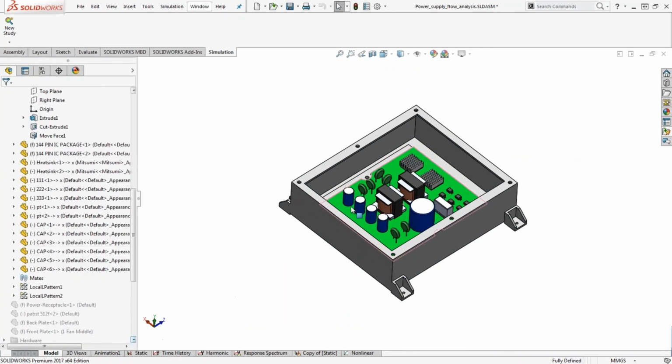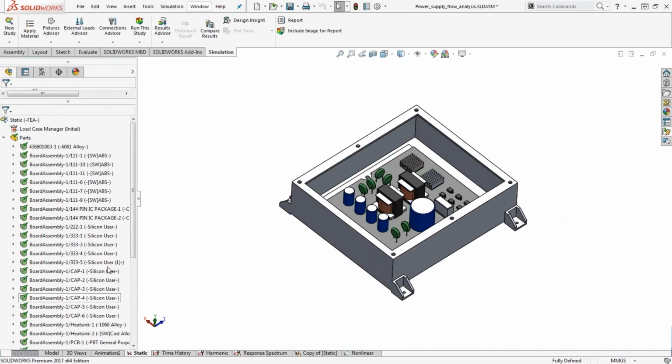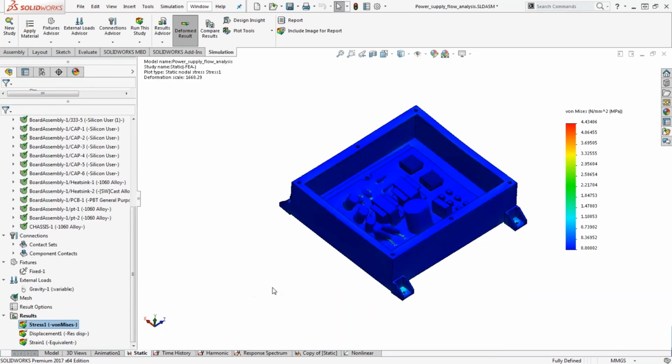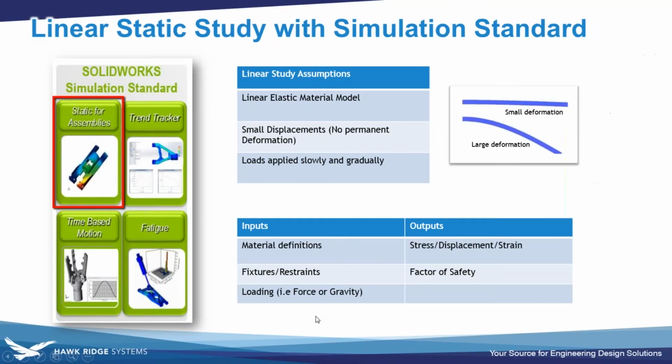So if I'm exceeding that yield strength, then that means that something has yielded or something is going into post-yield, where those max stress results are probably not going to be as accurate. I can make the assumption though that maybe something is breaking or maybe something is reaching a high stress where I need to do some sort of design change.